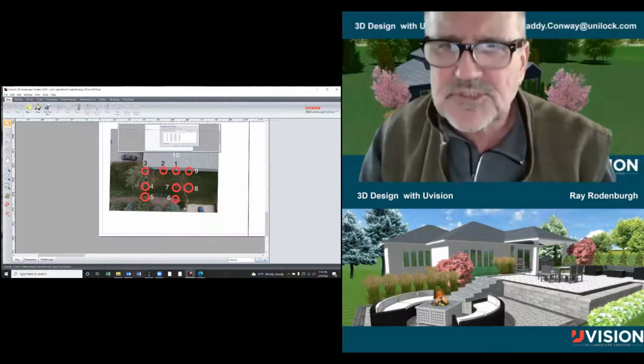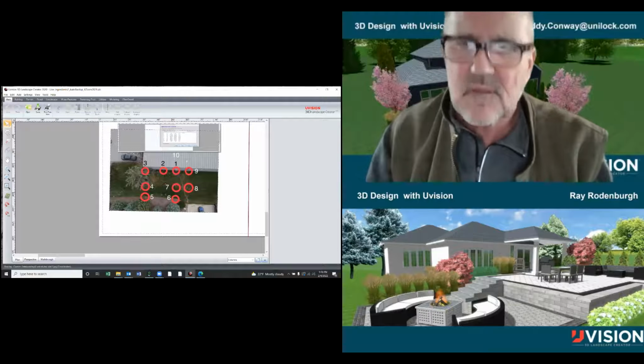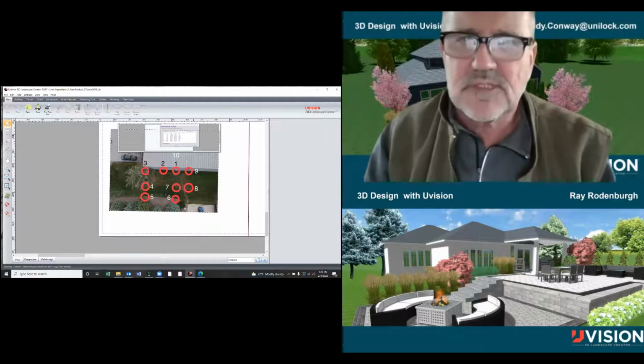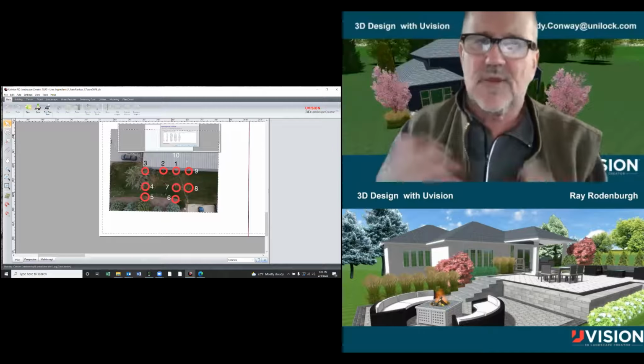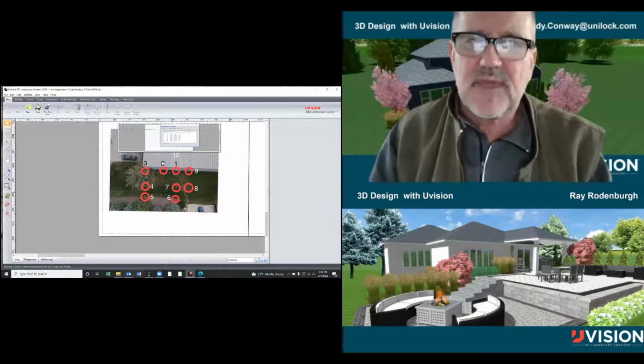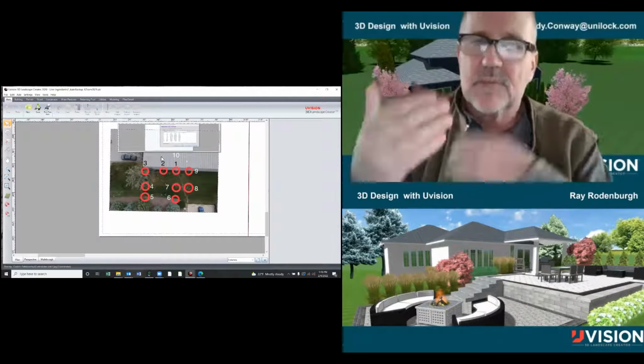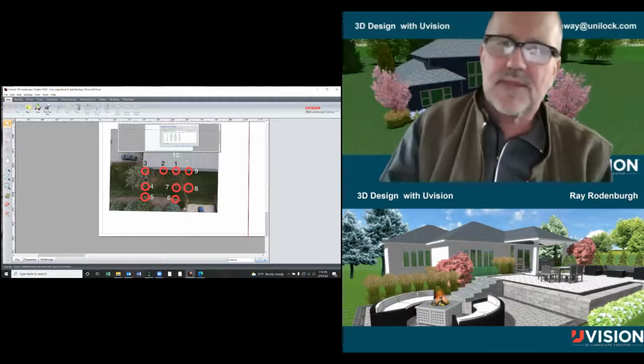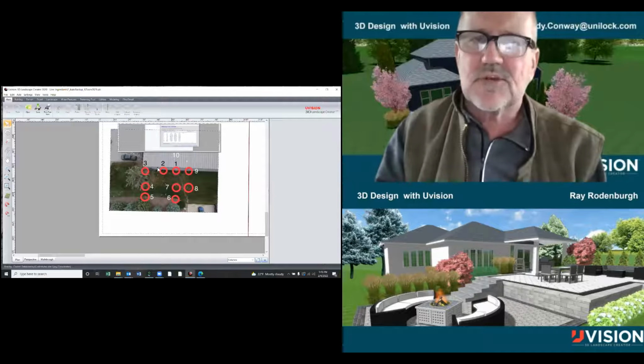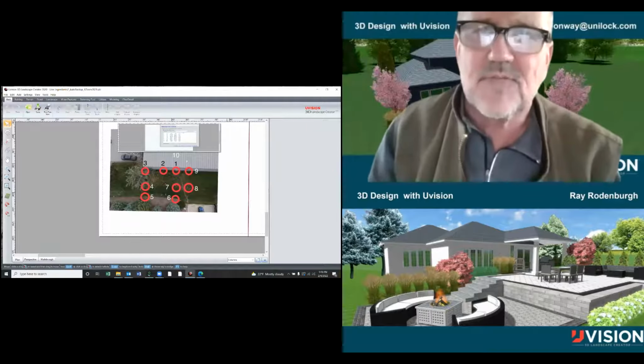I might have measured this point here at 15 feet. That's how I scale the drawing. The sidewalk could have been 3 feet wide, whatever. The length of anything on there gives me my scale, and I put that into the data. So this is just a doctored photograph of what the drone took by me adding these big red circles so I can visually see when I'm designing.